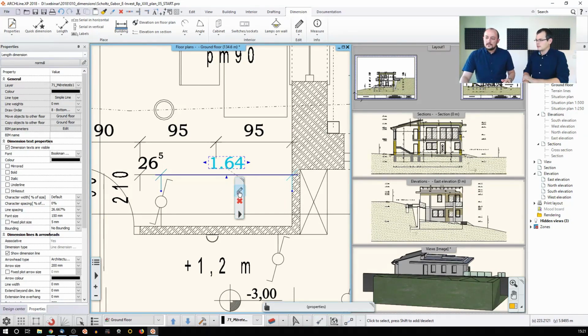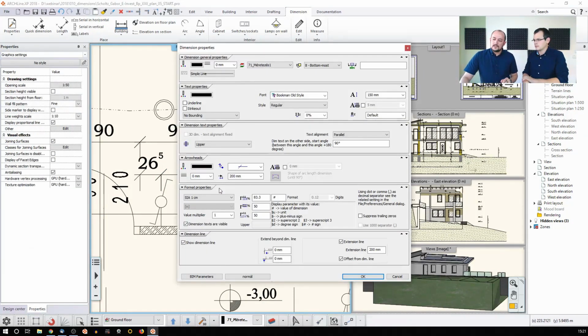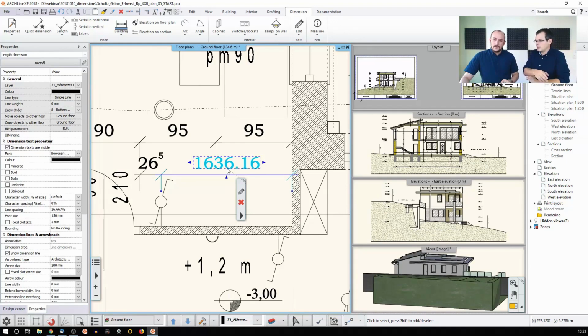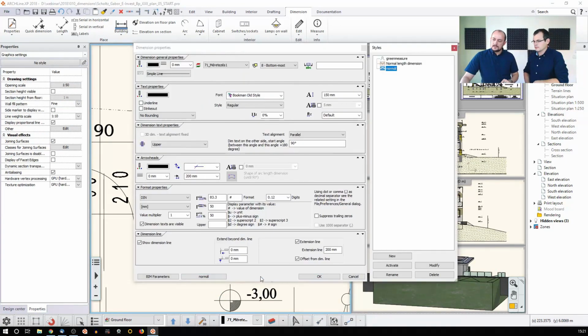You can go back to change the settings, and you can actually change something like DIN, and in that case you can even change the unit system that you are using. You can change to millimeters and say, okay, represent it like this, but only for this measurement. So you didn't save this as a style, you just decided that this should be different. Yes, if I want, I can add a new style and say, these are length dimensions in millimeters or something like that.